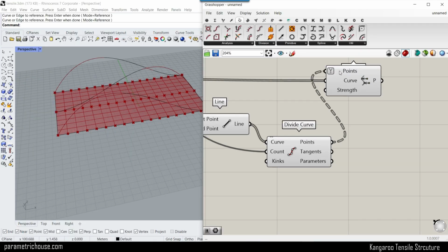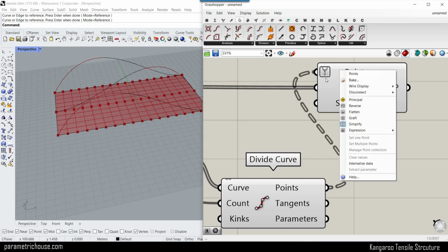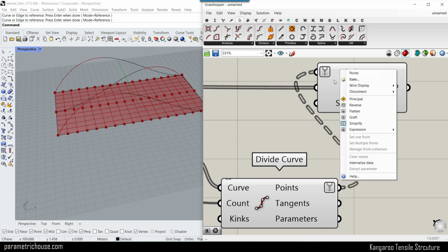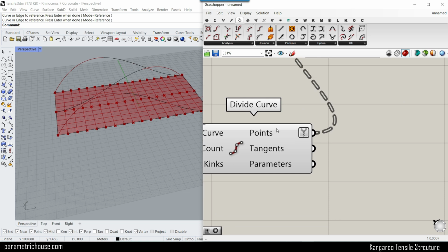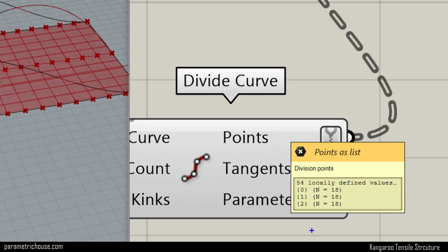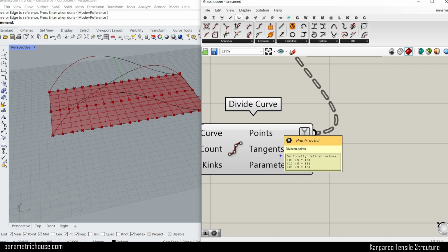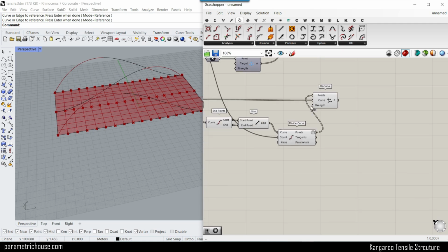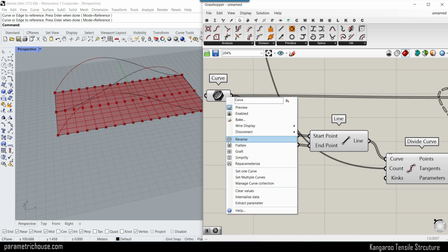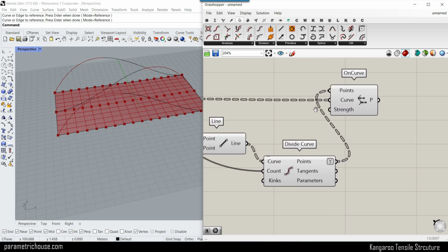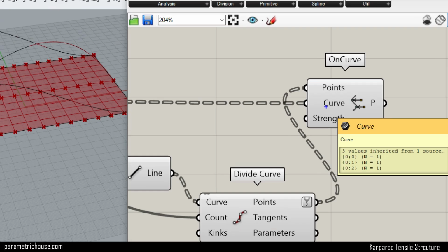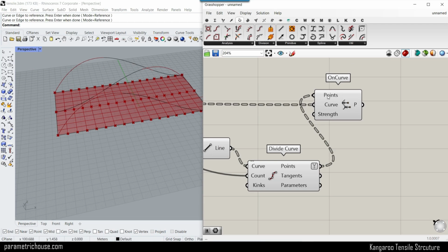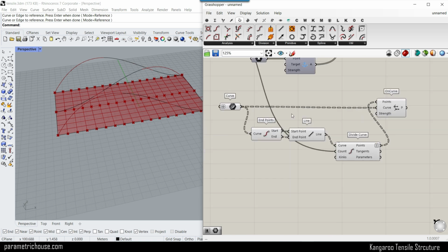And the problem here is that this is 3 groups, and I just simplified that to make that. You can also simplify it here, so you can see the output. Those zeros are gone, and we have that 0, 1, 2 group. Okay. The problem here is that this curve is not in a group. How can we fix that? You just have to graft this curve. It's going to put each of those curves in one group, and then we will have the groups here. And you can see that both of them are okay.